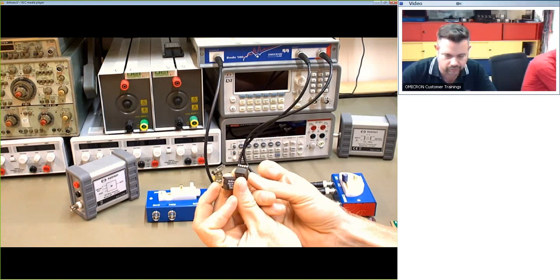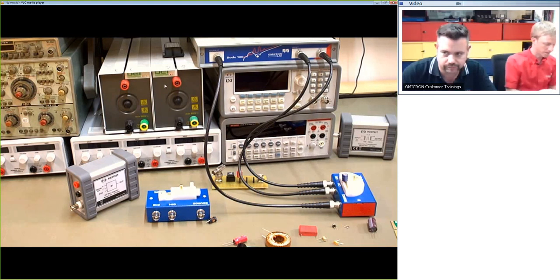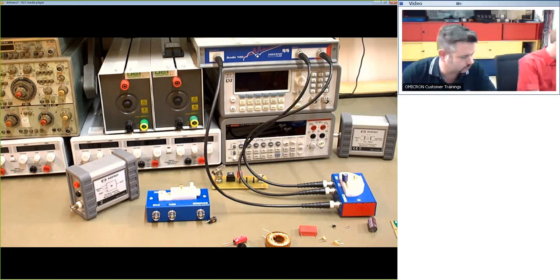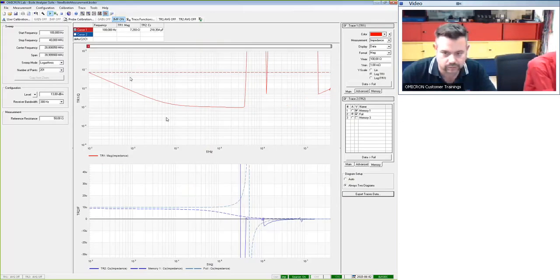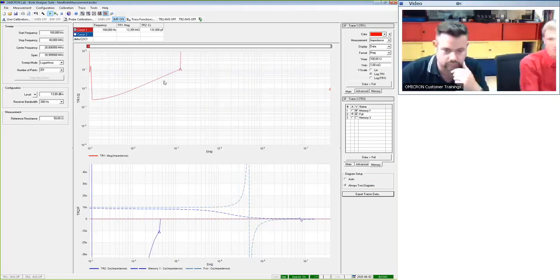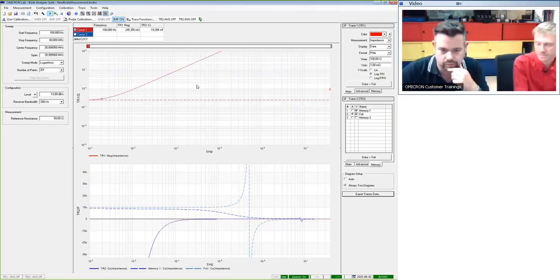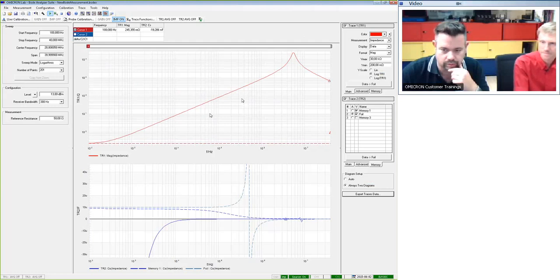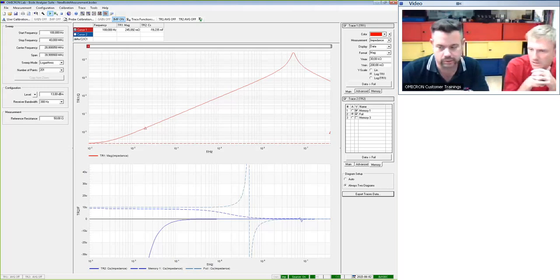We'll now first measure the primary side inductance by using the transformer that has open ends on secondary. I now remove the capacitor and I place in the transformer primary side. So again, we can see the impedance rising 20 dB, and we calculate inductance in the second phase.